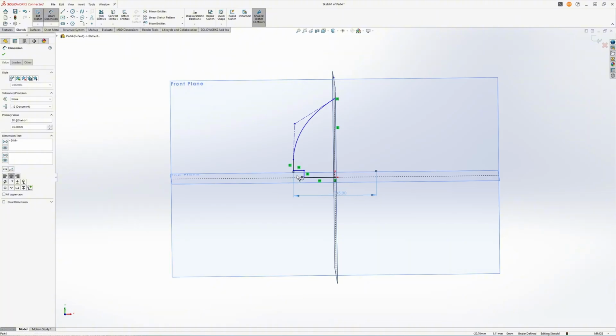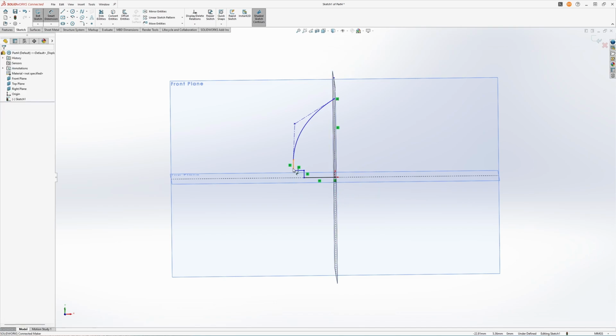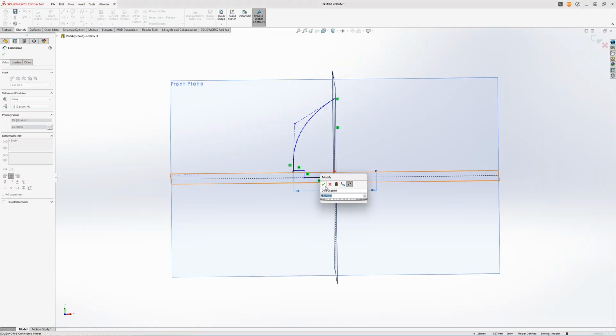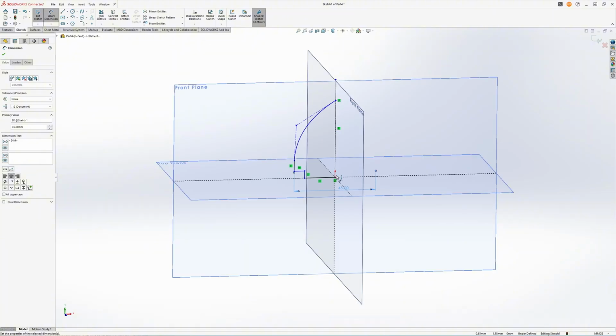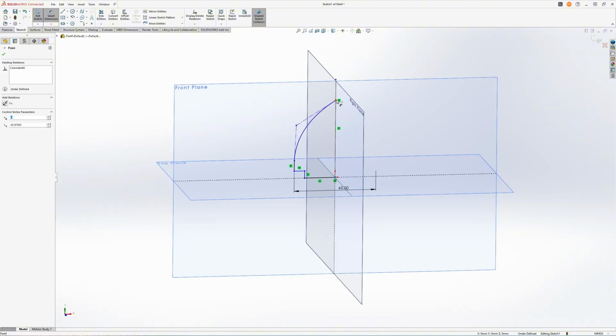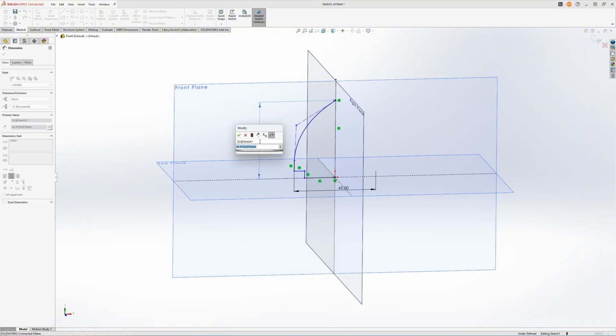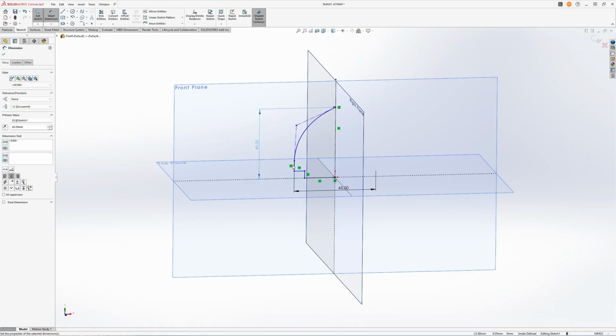So the way I did that was I selected this outer diameter that I want to select, and then I clicked the center line and I dragged over. Let me try to do it again so you can see it. Center line. Oh, sometimes it just snaps like this, and it knows that you want to do a diameter like that. And let's also do a constraint on the top of it. Let's say 40 will do for that.